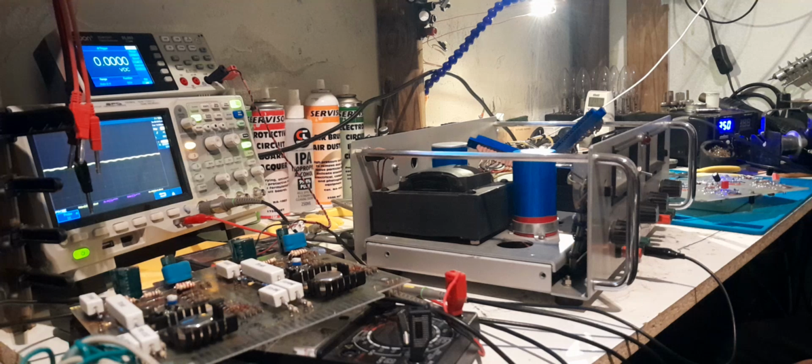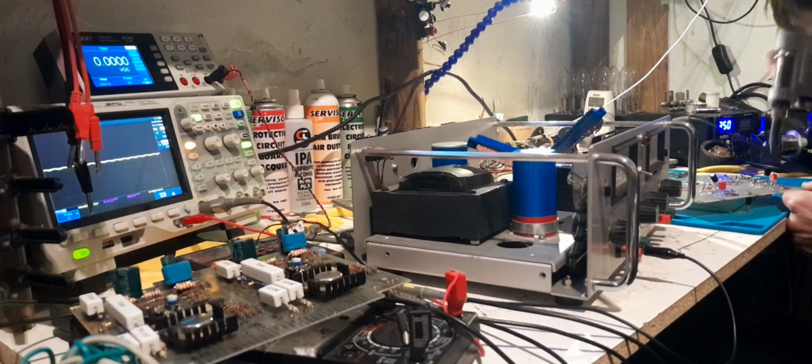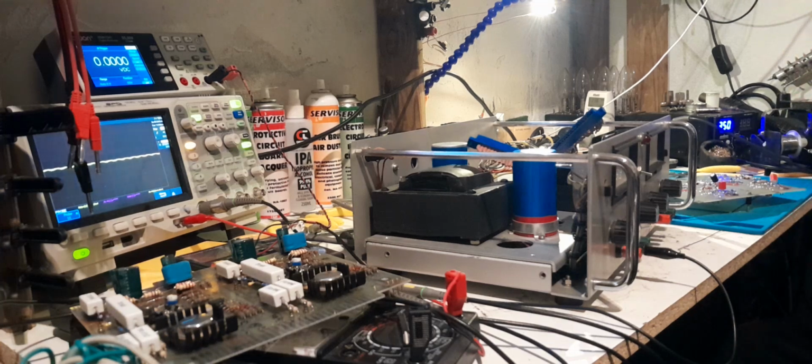So I'd imagine when I slow them down a bit, it would bring that into the ballpark of the LM301, and it's not having an effect on oscillation, so I don't think it is that. We'll have a look at the data sheet after I've taken this chip out, and we'll just have a look at how much current the output can actually sink.